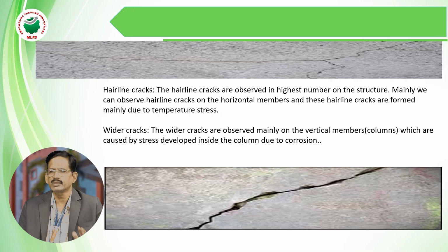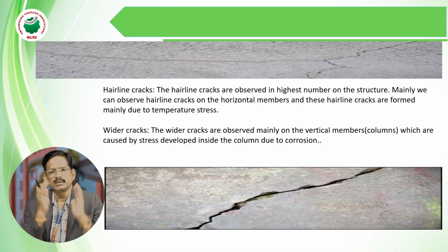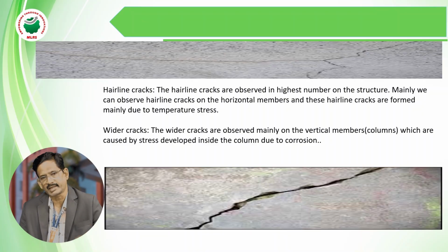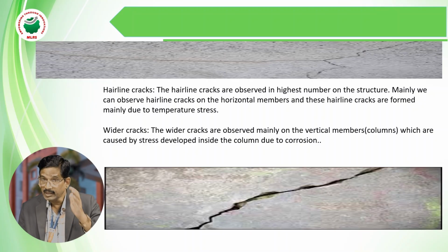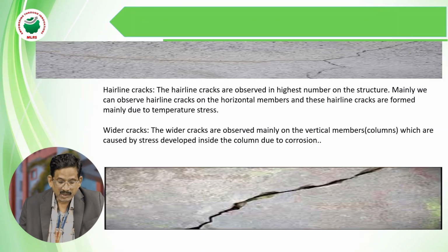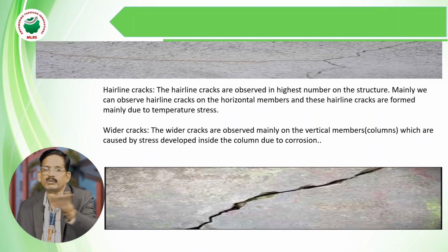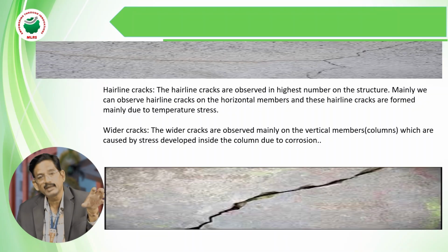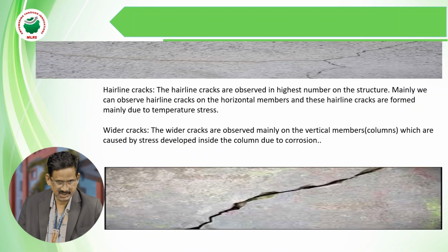In this, I have to observe physically what problems are there in the particular building. First, hairline cracks. So what are hairline cracks? These are observed in the highest number on the structure itself. Mainly we can observe these cracks on horizontal members, and these hairline cracks are formed mainly due to temperature stresses.